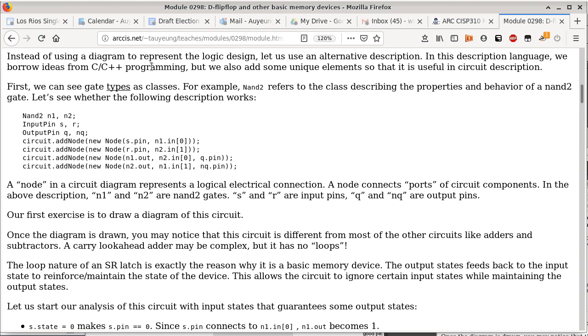The density you can store on a single track is limited by the media's physical limitations, because in order to change the magnetic field of a certain area on the platter, it takes time. That time is your real limitation of how fast you can store or retrieve data from a hard drive.